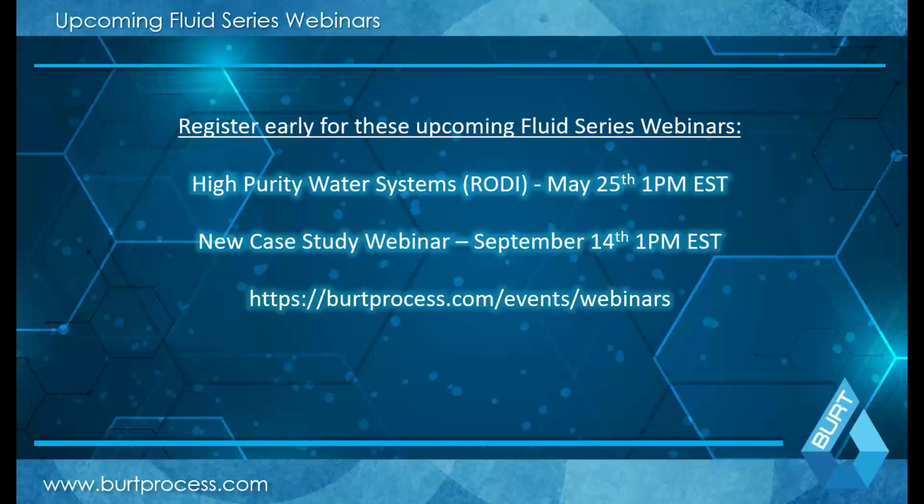Could you please expand on the design considerations of the reagent recirculation loop? Of course. There are two different ways to do reagent injection. In a lot of traditional pH systems, you have those downpipes, which I showed you, and you basically do drip chemical injections. As your metering pump pulses, it drips through a foot valve into the volume of your tank, which then gets caught into the mixer backwash.